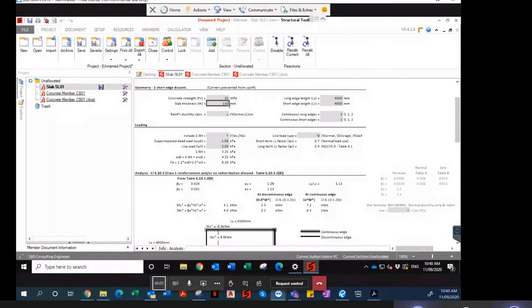And then when you consider the lapping of bars, in some places there'll be another 16 mil. So in those locations, your concrete between the bars is only 30 mil.